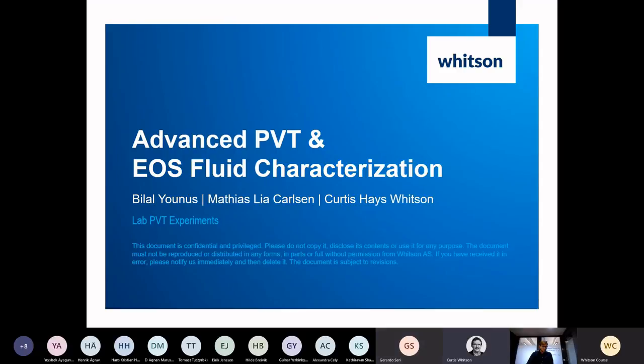And that becomes important data in the EOS tuning and also the fluid initialization both. So you use these samples away from the GOC that are not in equilibrium with each other to create that equilibrium GOC gas and oil. And that's really useful data for tuning the EOS and initializing the reservoir fluids spatially.